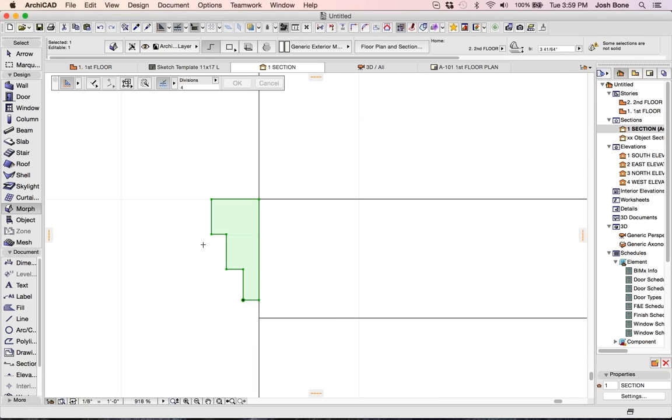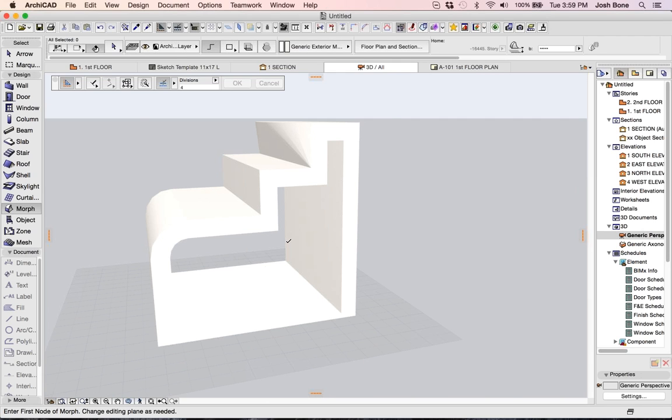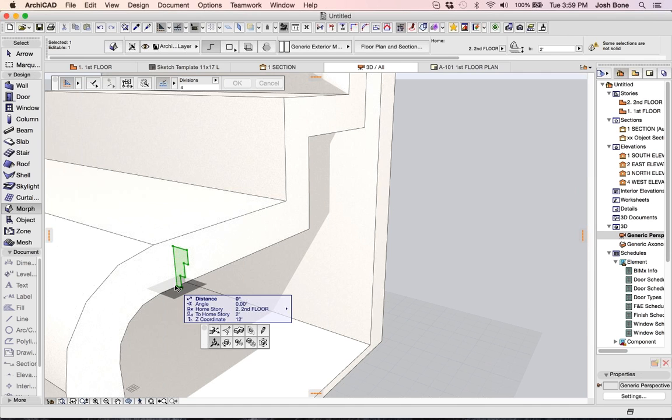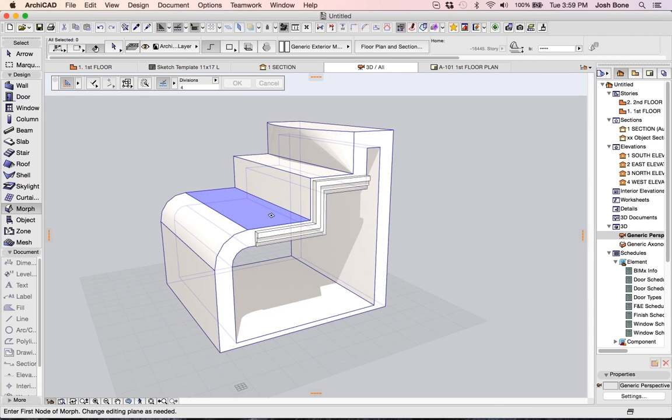And from me drawing that plane now, if I go back to 3D, here's this shape. And from this shape, I can move this into place. Wherever I choose to move this, let's say I want to move this back down here along this angle, I can go back in here now and have this use a similar type of follow me. And I can move up, I can move around, I can adjust, I can change each of these materials so that you can see we can create very complex shapes right inside of ArchiCAD.